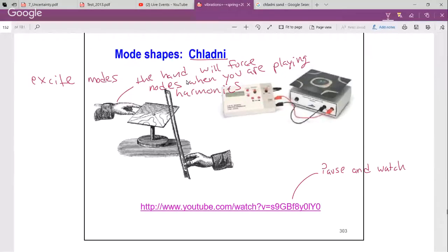So another little lesson for you. Not only can we have modes on structures, we have acoustic modes in volumes. Because of the carpeting and the ceiling material, it'll absorb some of it, but we'll still probably excite the volume. There will be enough energy to create acoustic modes. At 1,000 hertz, the wavelength of a mode is about a foot. So if you're in excruciating pain because the frequency is hitting your ear, because you happen to be at an antinode rather than a node, you can plug your ears or just move your head a little bit.